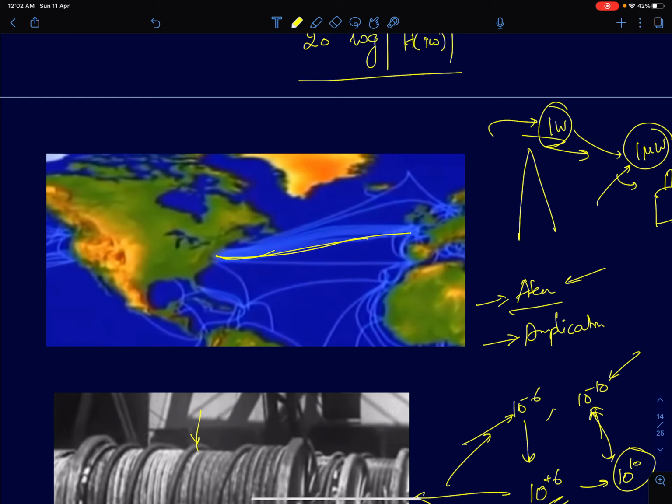One thing that engineers had to ensure is that as a signal travels along this wire, it induces power loss. So engineers were dealing with estimating the power loss. Once we know the power loss, then we can insert an amplifier in between, which will amplify and give the power back. So whatever power was lost, it's going to restore it back. These amplifiers were called repeaters.